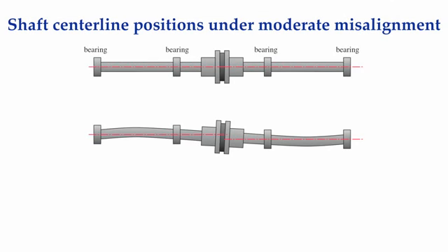Let's now take a look at what is going to happen to our shafts if we begin to misalign them. The dashed red lines define the center of the bearings for each independent shaft. What we're going to do here is intentionally begin to misalign these two shafts by lowering the shaft on the right. If there is a slight amount of misalignment, then the flexing points in the coupling should be able to accommodate that with very little trouble.